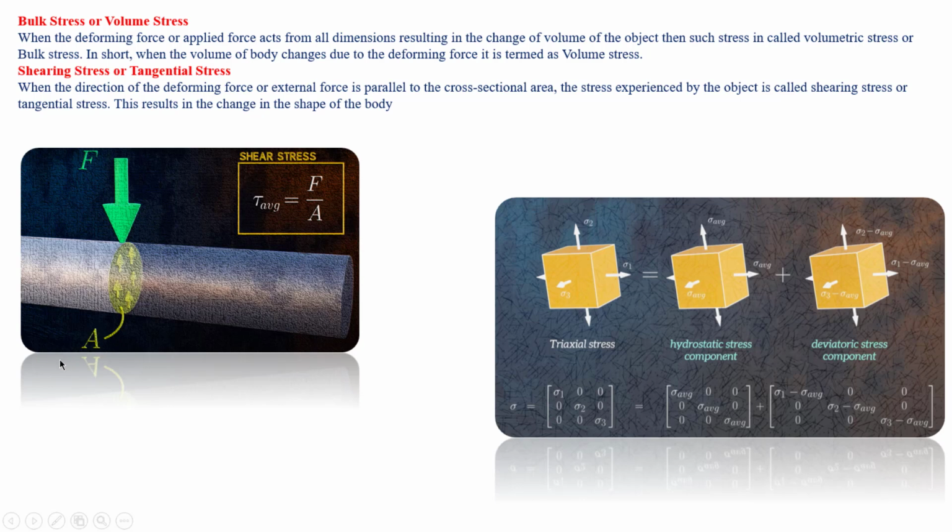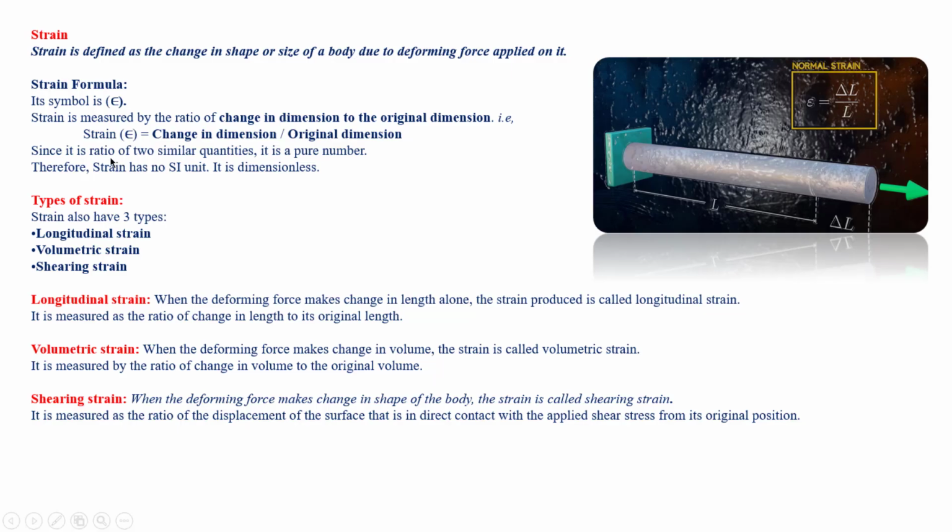Remember that. Shear means, if you take two solid bodies and rub them, or if you take your two hands and try to move them against each other, they will face shear. The force is parallel to the cross-sectional area. Well, that is the basics about stress. In short: compressive, tensile, shear stress, and volumetric stress, complete.